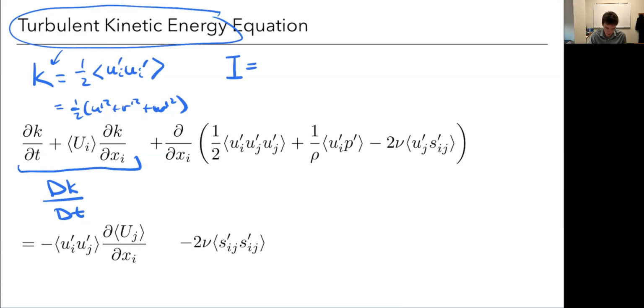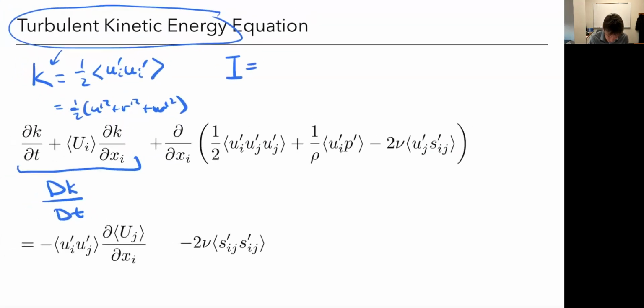So I'll take K, and I want to get rid of this half, so I'm going to multiply by 2, and I'm going to now divide by 3 because I'm going to take a mean, and I'm going to take a square root. So it's a root mean square of these velocity fluctuations. So I take all these velocity fluctuations, I square them, that's the square. This 2 cancels the half. I divide by 3, so that's the mean, and then I take the square root.